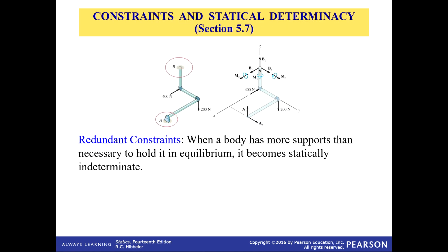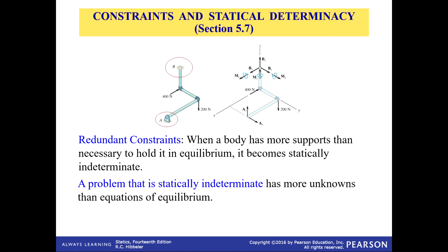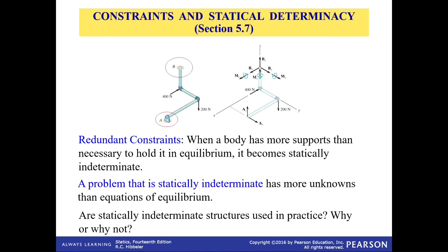So that is the message behind this particular next slide. In this particular case, you have a problem that has more unknowns than equations. You can see 1, 2, 3, 4, 5, 6, 7, 8, 9, 10, 11. It looks like there's 12 unknowns in this particular case. You've got 6 equations. You cannot solve this problem. It's statically indeterminate.